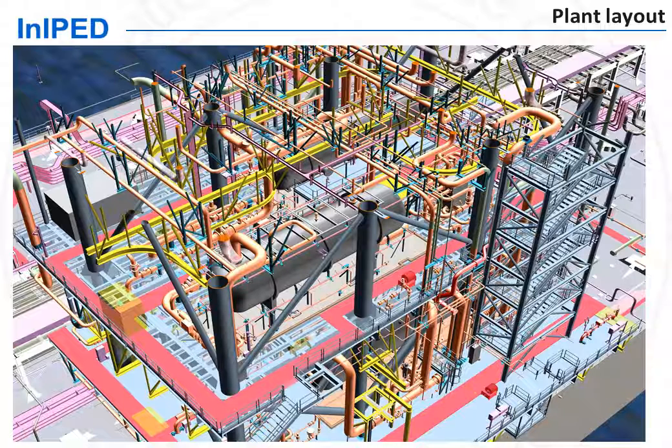Indeed, overhead access with a crane for removal of parts is not feasible offshore as it is onshore, as equipment are stacked on several levels. Therefore, parts must be moved by means of monorails to the edge of the platform where they can be picked up by the crane.